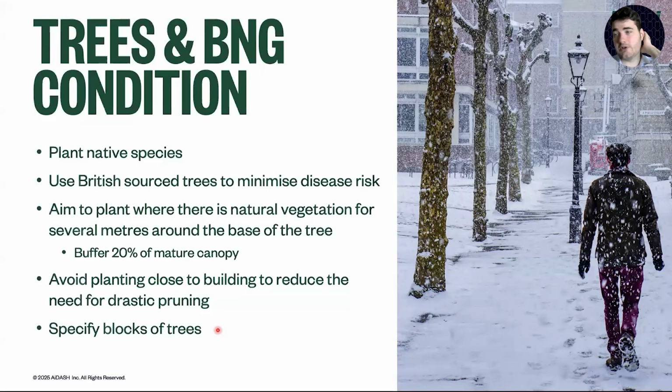And avoid planting really close to a building such that you're later going to have to cut off a limb of that tree in order to prevent it from impacting traffic or impacting a building. If you're doing that, that's a fault, and that was a mistake that you've made in your own design. We don't want to be doing that. That's a specific condition criteria we're trying to avoid. So plan for the size of the full mature tree.